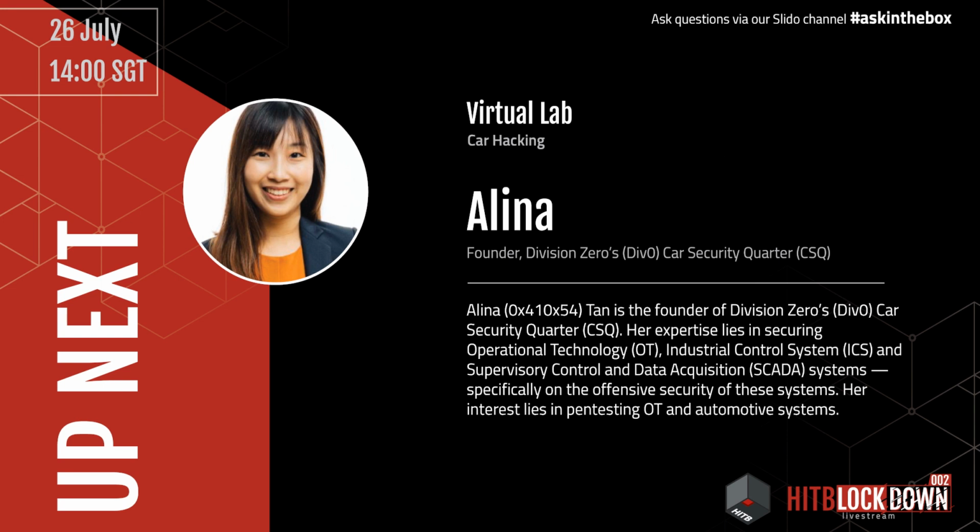Your accelerator, if it's drive-by-wire, is usually FlexRay, and usually you wouldn't really see much CAN bus in there, but there are also cases where CAN bus is present as well, depending on the OEM. For the steering wheel, usually LIN bus, but some manufacturers prefer to use Automotive Ethernet. So it depends from manufacturer to manufacturer. The ones that we went through earlier are the commonly used protocols in vehicles.